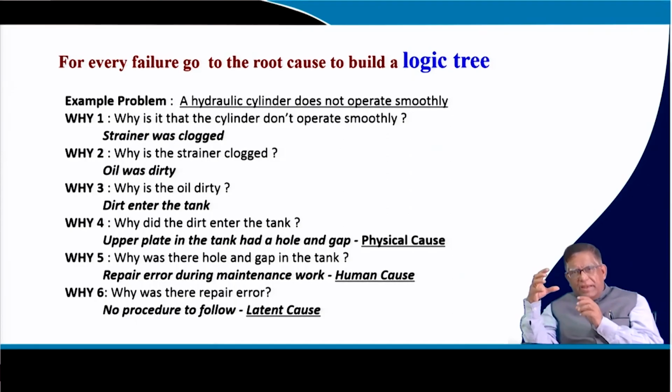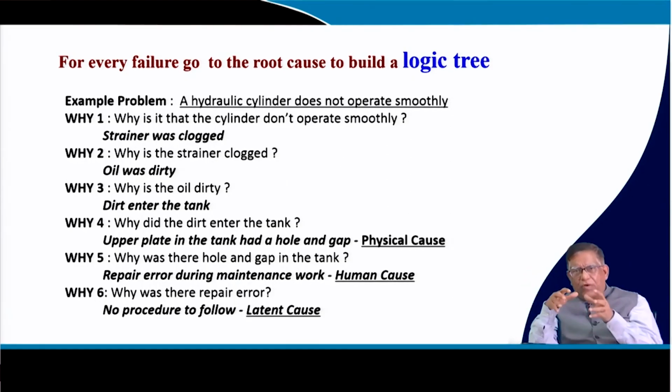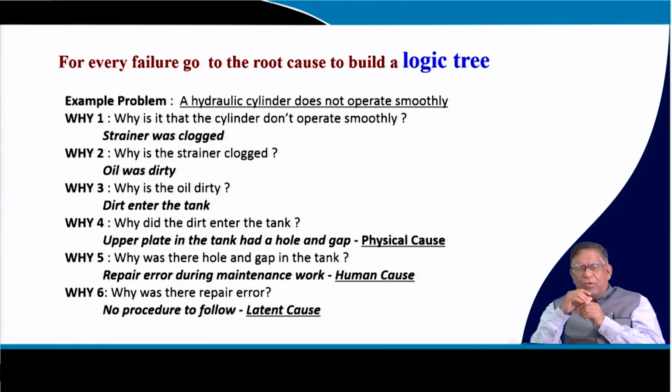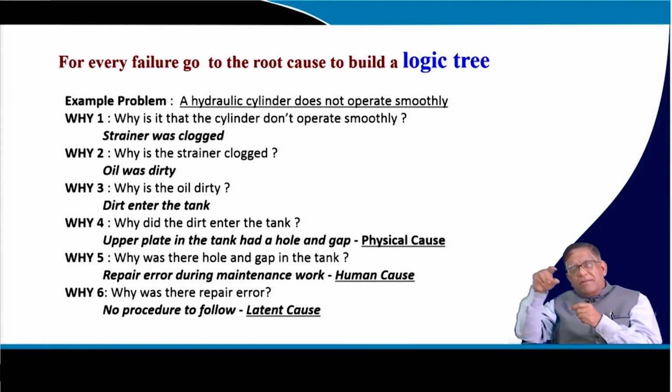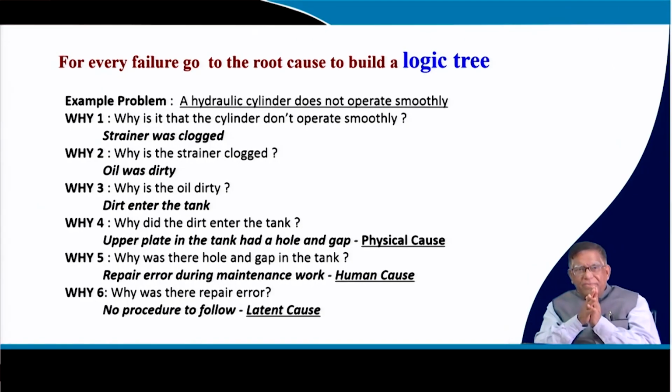In the tank, if there is any upper cover, any seal or any gasket, you need to check that as a physical cause. Or there could be other things also. You need to see where the oil has interacted, which portions it has lubricated. In that portion, if a bearing is moving, whether dust or dirt particles are coming from the different parts inside the machine.